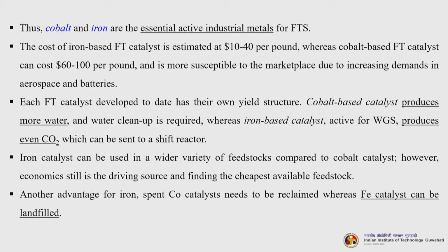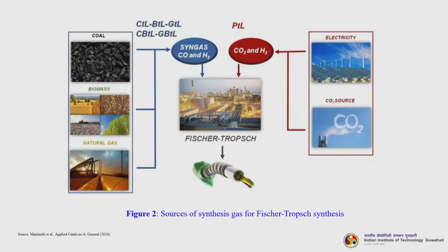So, iron catalyst can be used in a wider variety of feedstocks compared to cobalt catalyst. However, economics still is the driving force in finding the cheapest available feedstock. Another advantage of iron: spent cobalt catalyst needs to be reclaimed, whereas iron catalyst can be landfilled.